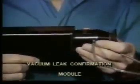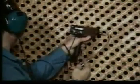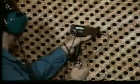As steam rushes across condenser tubes, it generates a noise with ultrasonic components similar to those of a leak. This sometimes confusing sound is called steam impingement. To differentiate between steam impingement and air-in leakage, use the vacuum leak confirmation module in place of the regular scanning module. Seal off the end of the suspected tube, isolating it from the rest of the tube sheet. Then listen and observe the meter.